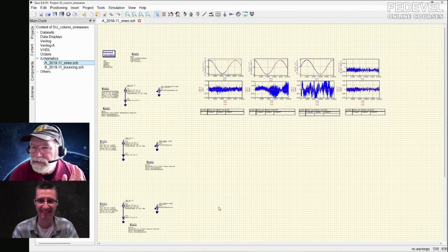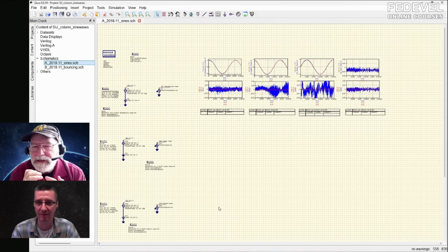So this does not do the field solver. But there's a free tool. When we characterize a transmission line, we describe it in terms of two parameters, basically: the characteristic impedance and the time delay. And that's the starting place for the simplest model for a transmission line, those two terms. It's lossless, but it allows us to calculate and simulate all the reflections associated with that structure. And so as a starting place, it's a great model. And that's what Qucs will allow us to do.